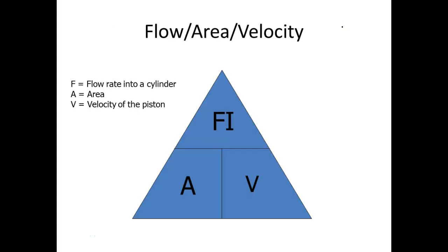So this is speed. There are two things we need to understand: how fast the piston or actuator is going to move, and also how much force is going to be generated. So what determines how fast an actuator moves? Not pressure. Pressure doesn't determine that either, even though we have to have it. It's the flow, how fast things move.